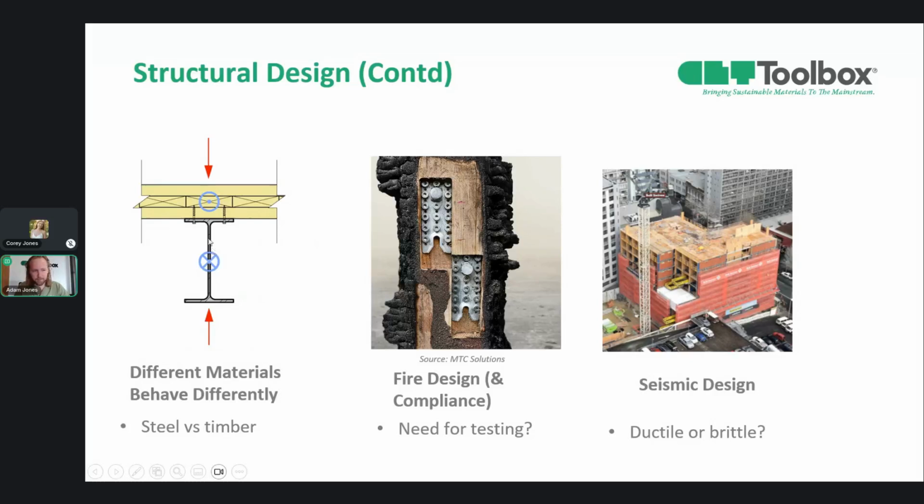So if you think about steel compared to timber and how it relates to a connection, a steel beam might conduct heat in the fire, and then that heat can be transferred through the fixing as well to have the charring perhaps start prematurely in the timber, which typically just chars at a gradual rate depending on factors like density and glue and things like that.